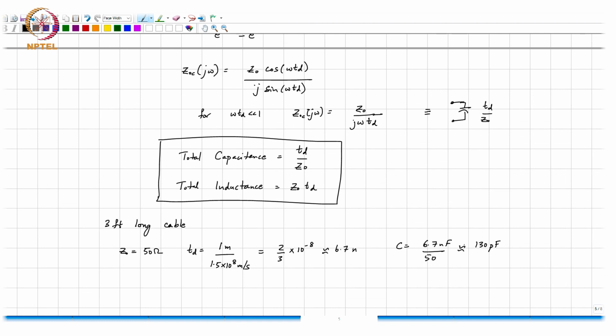Does it make sense? Right? Okay. Which is why a 1 farad capacitance is a huge capacitance, right? So, this is like a 3 foot long cable, right? And it's got a capacitance of only 100 picofarads or so, right? To get microfarads or nanofarads, or farads of capacitance, you better pack things very, very, very